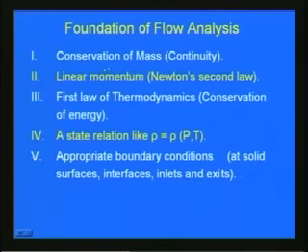Five important foundations of flow analysis are: the conservation of mass, based upon which in fluid mechanics we derive the continuity equation; second, the linear momentum, based upon Newton's second law we can derive the momentum equations; third, the conservation of energy, or from the first law of thermodynamics we can derive the energy equations; then the state relationship between various fluid properties like pressure, temperature and density; and lastly the appropriate boundary conditions at solid surfaces, interfaces, inlets and exits.